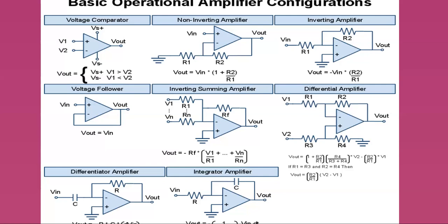You can make a differential amplifier. You can make an integrator, which in essence is a very low pass filter. Or you can make a differentiator, which is taking the derivative. So you can actually do calculus.